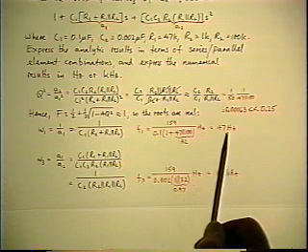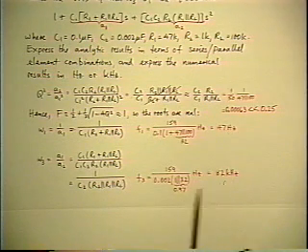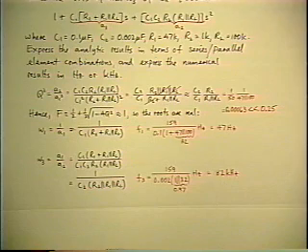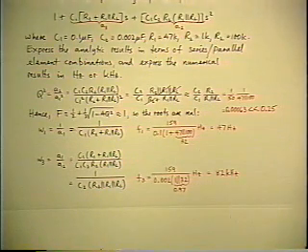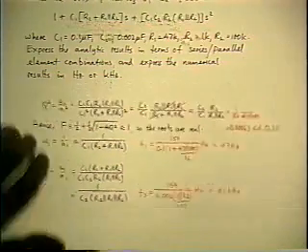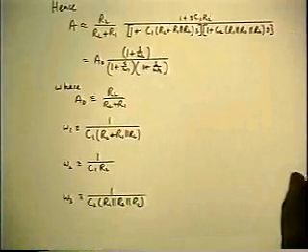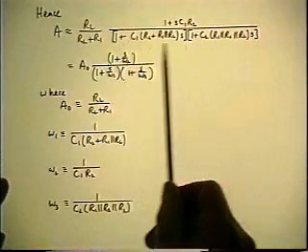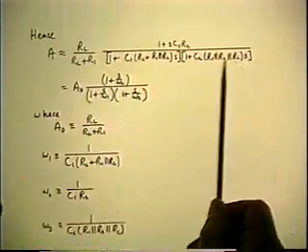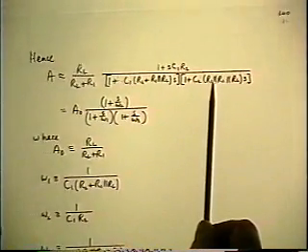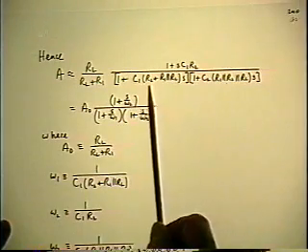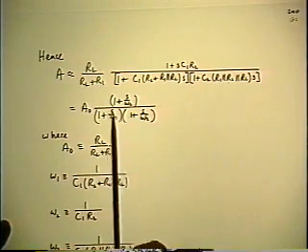The result comes out, the two roots are 47 Hertz and 82 kilohertz, which verifies the two roots are not only real, but well separated, which is the consequence of a very small value of Q. So here's the assembled results. This is now the factored quadratic in the denominator, where these are the approximate real root factors, assuming the f is equal to 1. And you see, no radical sign. Here are the two roots.